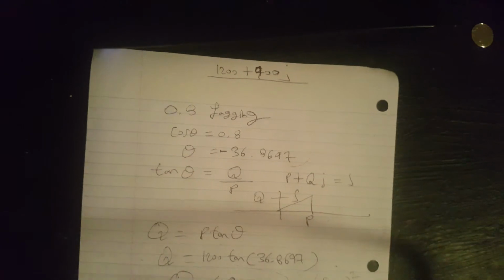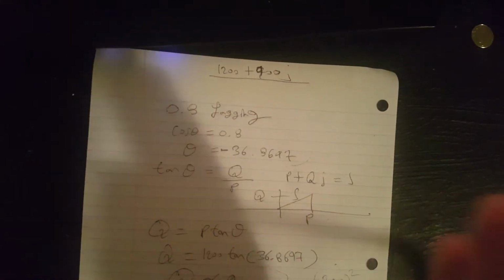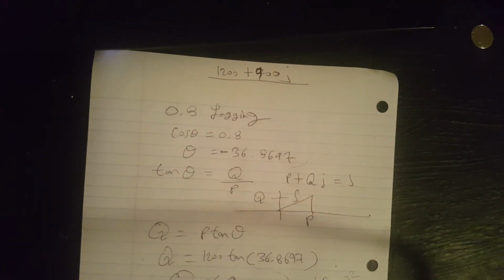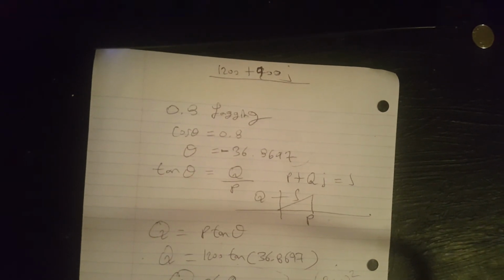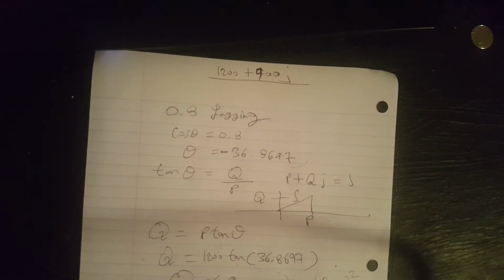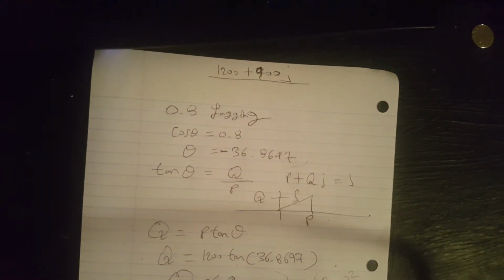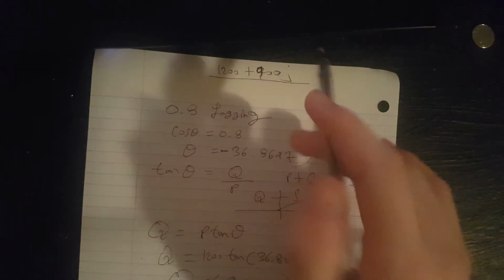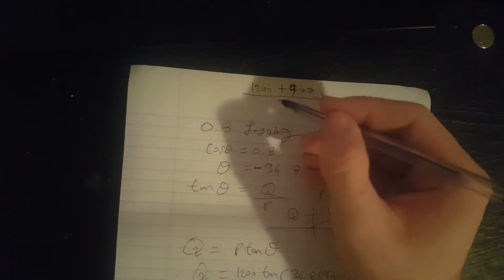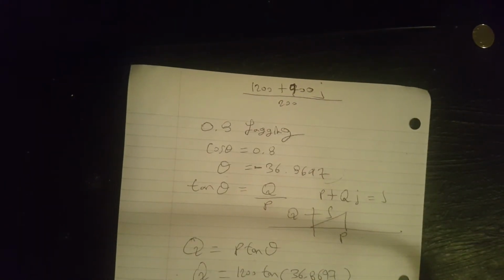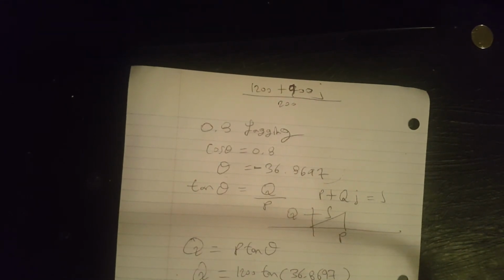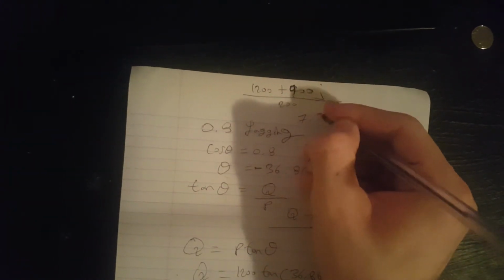This is 900. This is my total part. 900, because that's what we're trying to get. X, which is 700, is just the compensation, the power that is the adjustment to get to 900. So the actual power is 1,200 plus 900j. If I divide that by 200, I get 1,200 plus 900j divided by 200. That'll give me 7.5 amps.